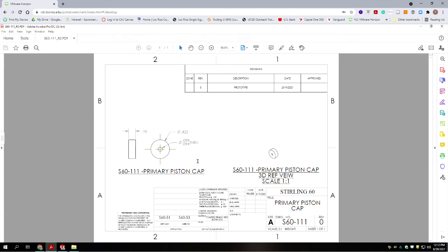Okay, and we have to figure out what the nominal average of the tolerance is. So this dimension, the actual center of the tolerance is 0.0965 is the center of tolerance. So that's the size we actually want to draw the circle.